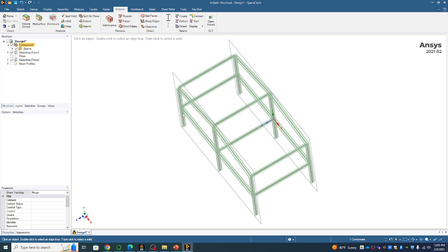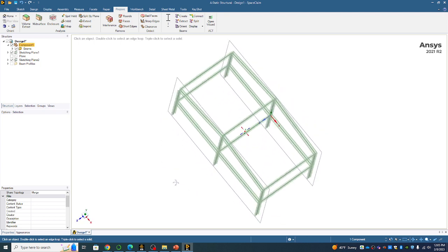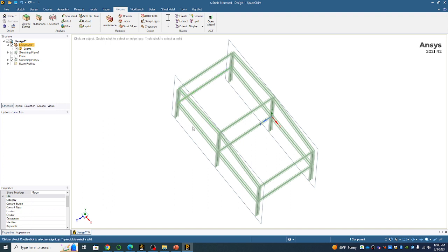And one thing you might notice is that the beams here, this 1, 2, 3, 4, the beams on this side, the 8 beams, their weak side is used. So we want to use a strong side, so they have a greater bending stiffness. So we'll rotate this by 90 degrees to get their strong bending stiffness side.